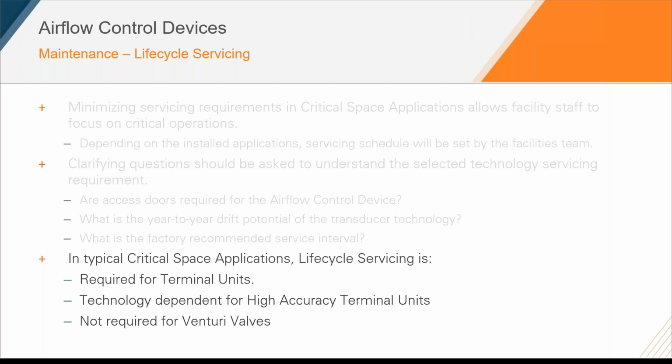For the high accuracy terminal unit, your life cycle servicing will depend on the technology you select. Some high accuracy terminal units will do better at minimizing the requirement for servicing, or minimizing the effect of dust, lint, and dandruff, compared to other valve technologies. And then lastly, for a venturi valve, typically that life cycle servicing isn't going to be required, mainly due to the fact that there's limited direct airflow measurement going on inside of that valve.